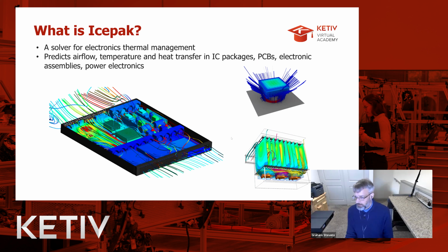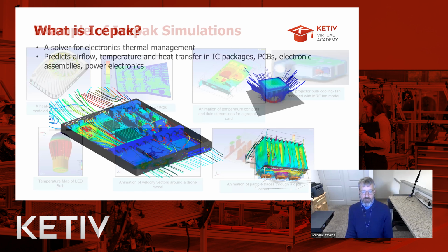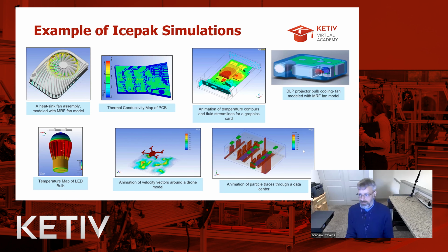It uses the Fluent CFD method and solver, but without quite as many bells and whistles in terms of the underlying mechanics of solving, to make it a little easier for electronics folks to just jump in. And these are some examples of these kinds of IcePak simulations where we're looking at airflow or conductivity, temperature contours, particle traces, so generally velocity of air or temperature impacts.